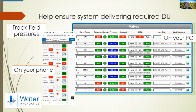Beyond that, we're also putting out sensors that are monitoring more than just soil moisture. There's a lot going on this page, but I wanted to draw your attention to the blue information in the middle. We're monitoring pressure across a ranch. Here we've got some very healthy pressure numbers, and that's a good indication that you've got distribution uniformity.